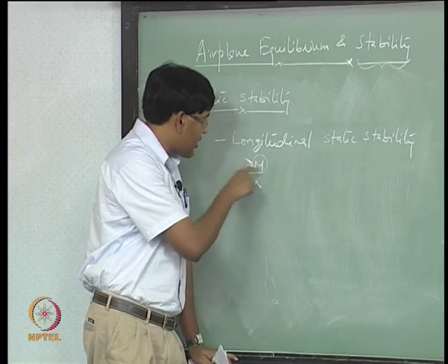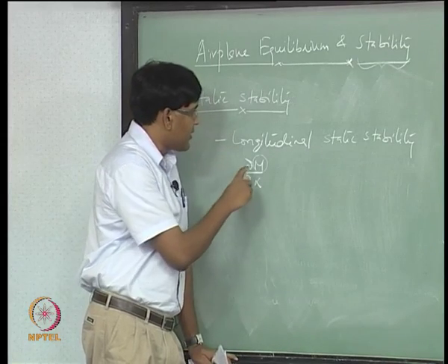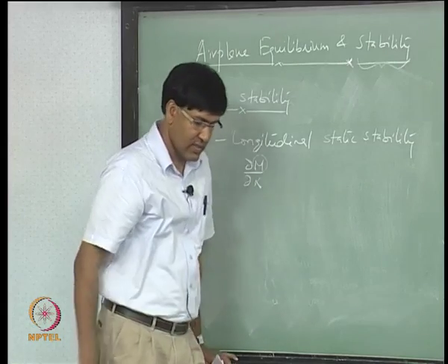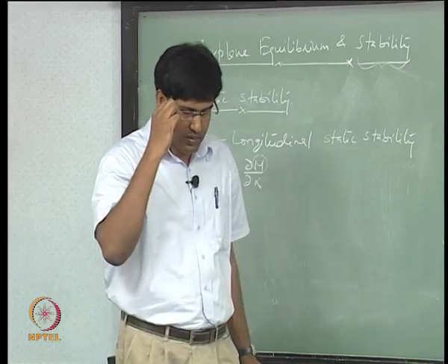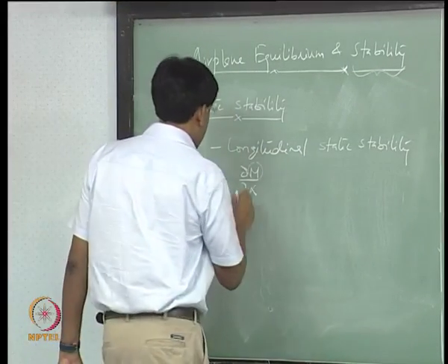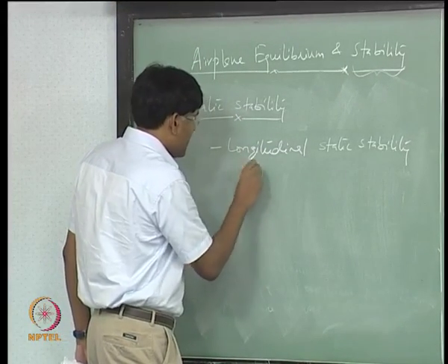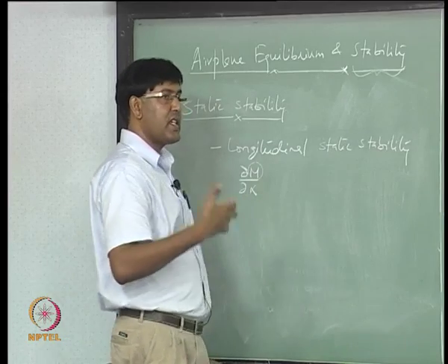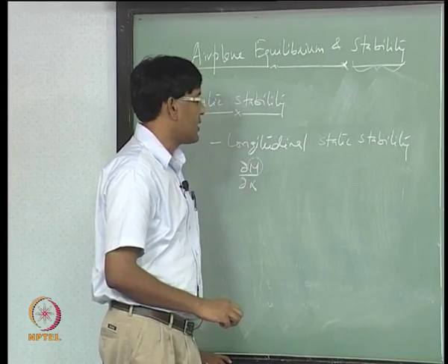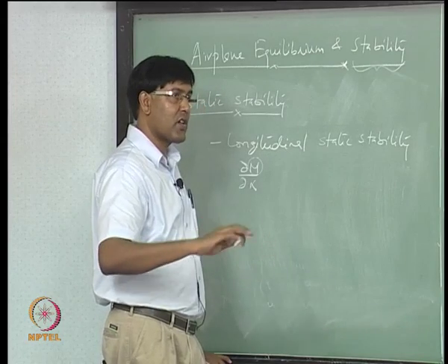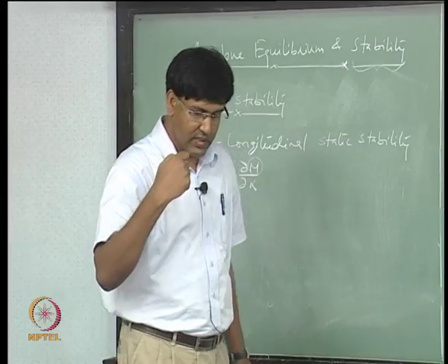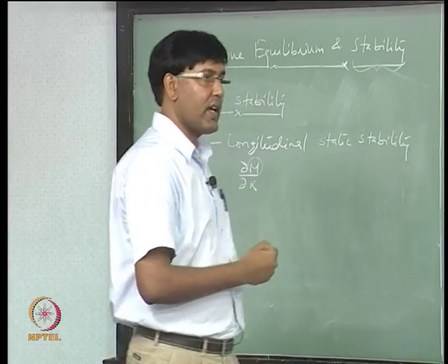It is not difficult to see that whenever there is a positive change in angle of attack, which is also associated with the pitching up motion of the aircraft, this pitching moment should be automatically generated. We are not looking at the control side, we are not looking at controls. Stability is the inherent property of the aircraft.